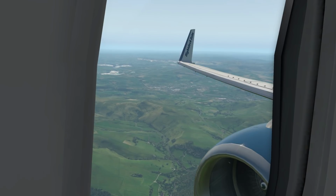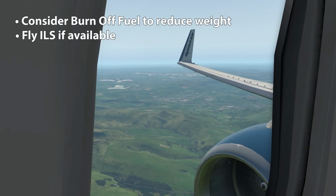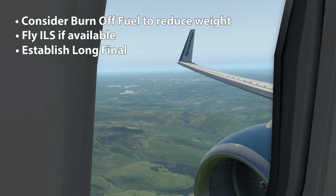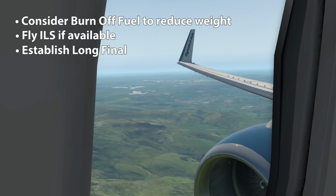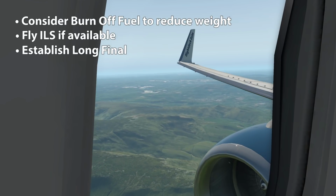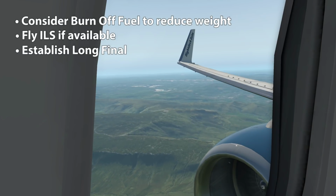Some of the things it mentions is to consider burning off fuel to reduce weights, as per the guidance in the QRH. If possible, fly an ILS, which is what we're doing today. It says establish a nice long final, and once you're established on a localizer, reduce to your final approach speed. And prior to glide slope capture, it's really important to lower the gear. If you don't do that, the speed will run away. In fact, in a 737, even with flap 5 extended and the gear up, it's quite hard to manage your speed sometimes. You might have to have excess drag, so we'll make sure the gear's down to cater for that.